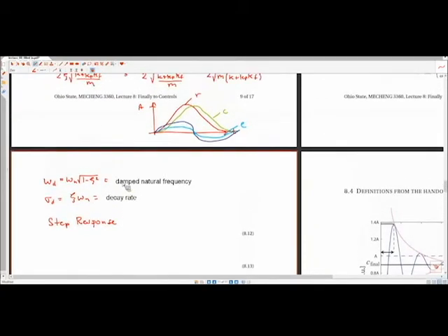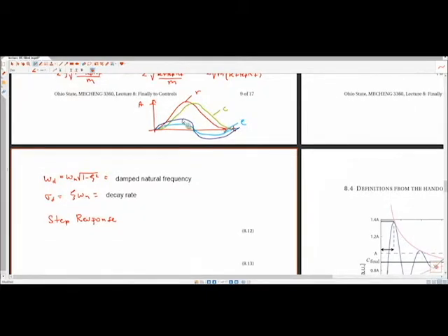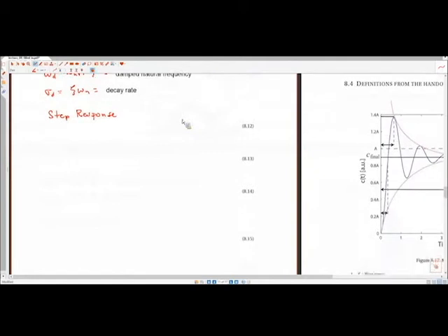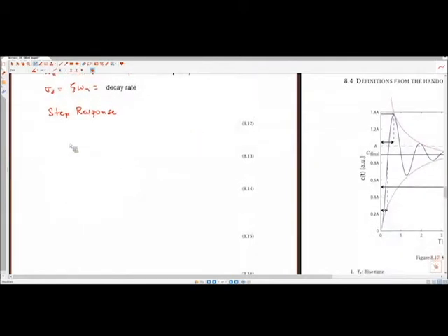This could be cruise control in your car, where you're saying go from 60 miles per hour to 65 miles per hour. You have almost an instant change of the reference velocity. And in a robotic system, this could be moving from wherever you're at right now to the position A bar at a certain point in time. It's a very simple input we can start to understand behaviors with. So the step response is something really fundamental that we'll use to discuss pretty much all performance.